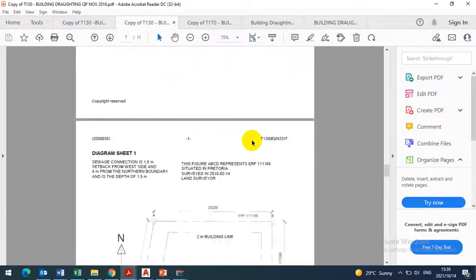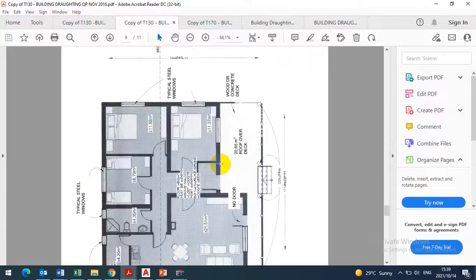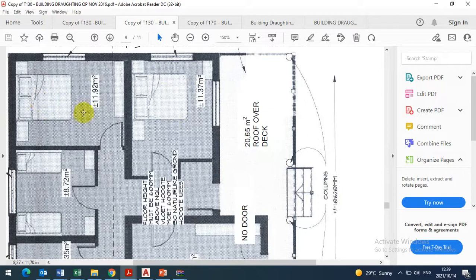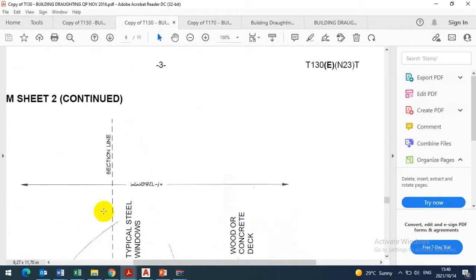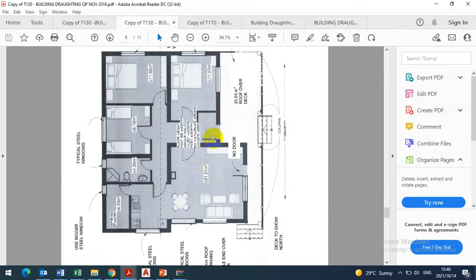So that these 2 rooms here, where is that floor plan? Okay, yeah, I want that. These 2 rooms, this one and this one, the length I'll use from here to here plus the brick thickness plus brick thickness, and the length I'll use from here to here must add up to that, the way I showed you on the other one. Coming down here, there are 1, 2, 3, 4 rooms here.